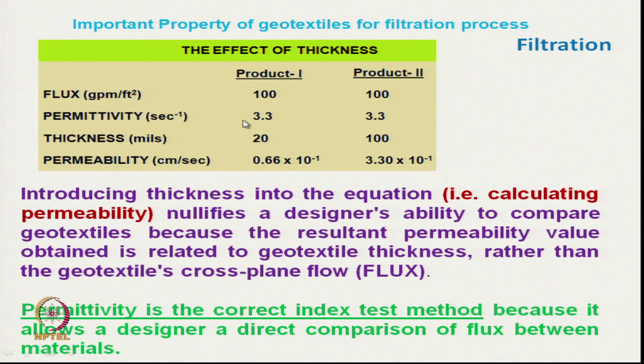So, this permittivity value does not change when the flux remains the same. This indicates the flux. If the permittivity remains the same, that means the fluid flow is the same irrespective of the fact that their thicknesses are different. Here we can see the permeabilities are different, so we cannot compare these two products effectively as far as filtration is concerned. These products are equivalent, but if we see the permeability, they are entirely different.